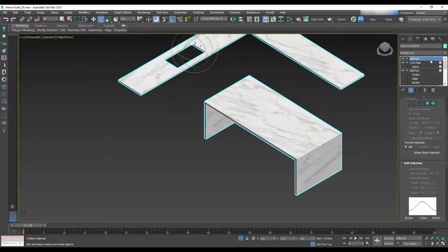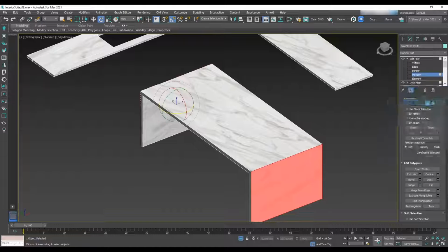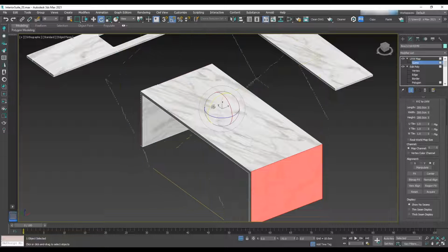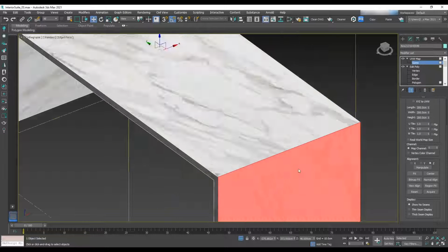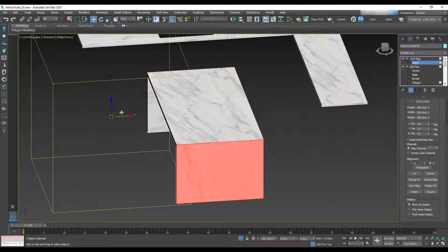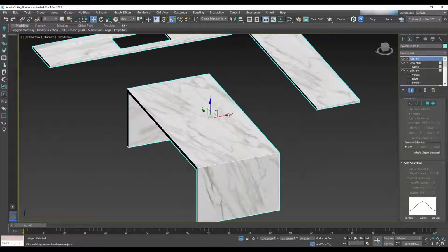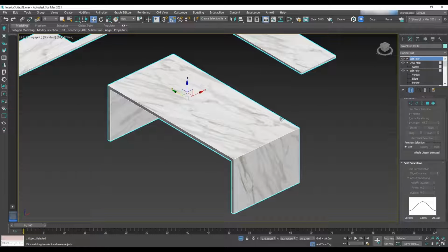on the countertop. We'll do the same thing for both sides of the countertop on the island, meaning selecting polygons and copy paste UVW map on top of edit poly and change the direction. Now I want to make countertop edges softer.